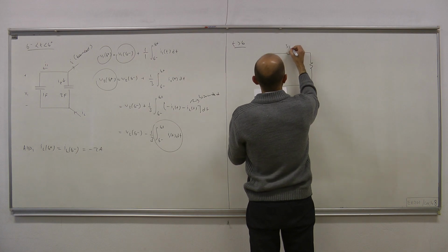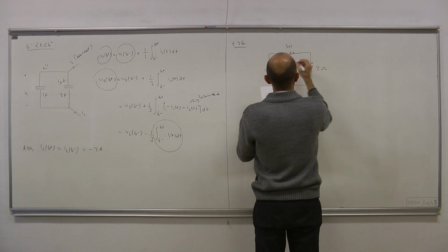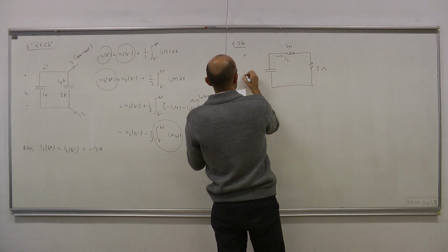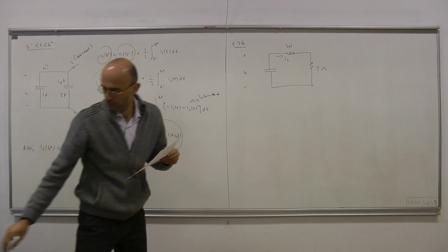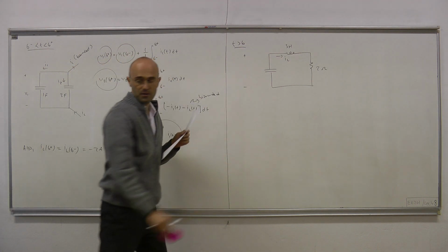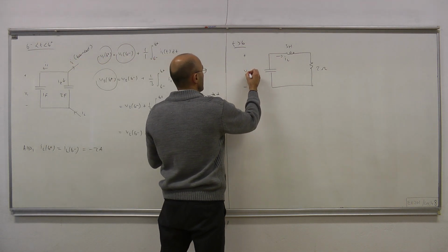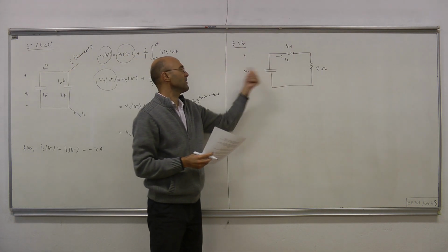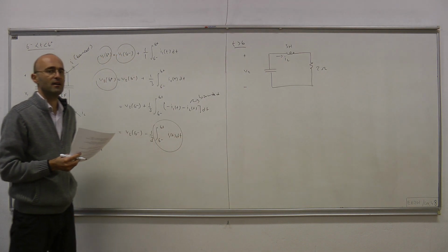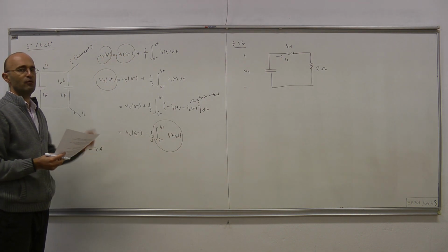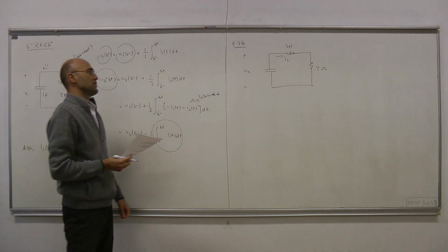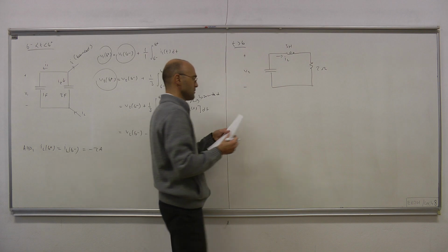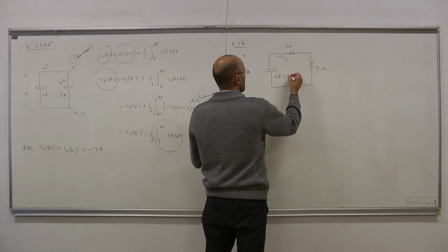Okay. This is 3 Henry, 2 ohms, so that's the direction of IL. Now we have E2 for this capacitor. Now the question is, what's that capacitance? We had 3 farads, and then that was parallel to a 1 farad capacitor, first capacitor. Therefore, we can replace those 2 capacitors with a single capacitor. The capacitance is the sum of the individual capacitances, 1 plus 3.